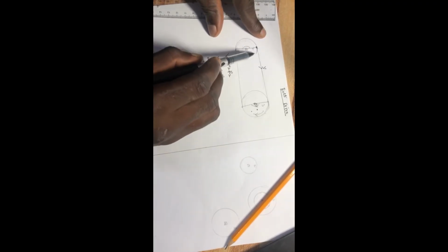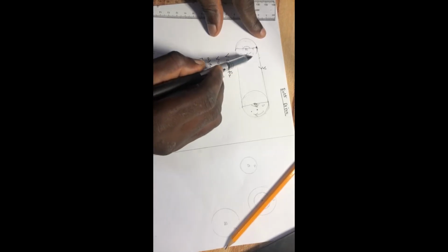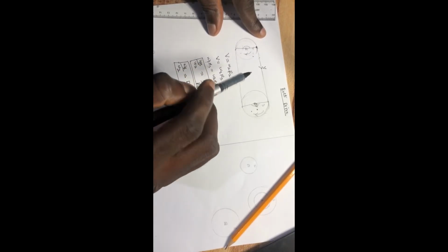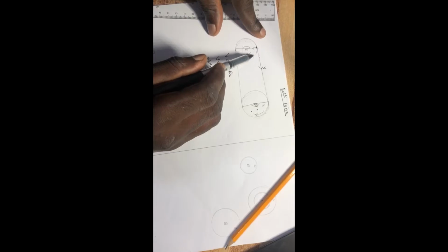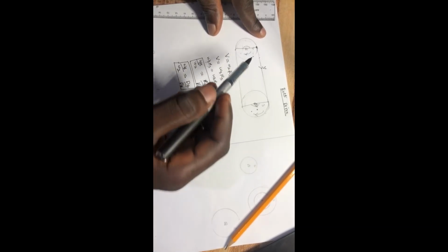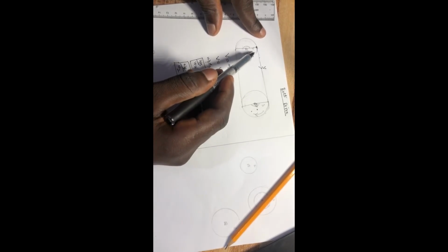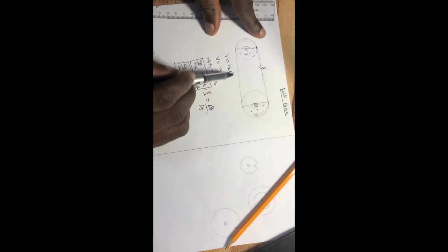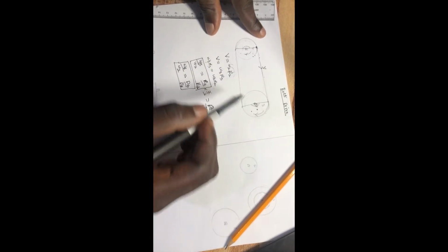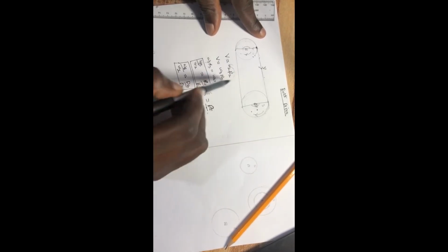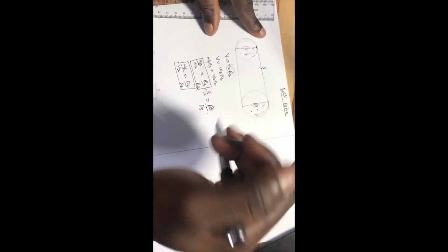Now, the transmission of the velocity to the belt relies on friction, the friction between the belt and the surface of the pulley. So in the case where friction is limited, right? There can be a situation where the friction is not enough to transmit all the translational velocity produced by omega 2 R2 to the belt. That means a portion of the omega 2 R2 will be wasted in slipping the belt on top of the pulley.